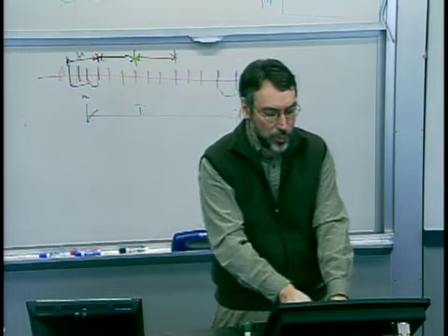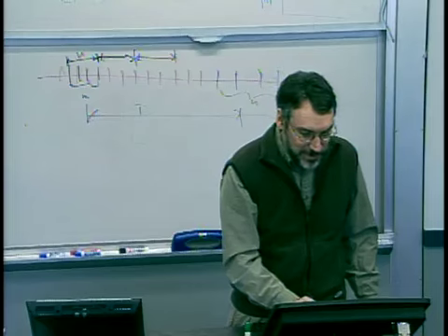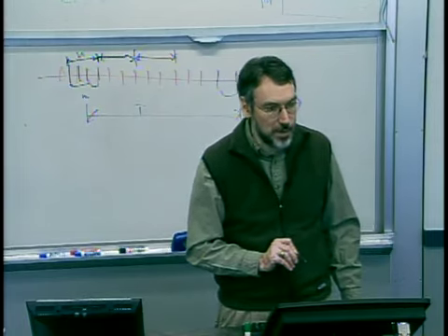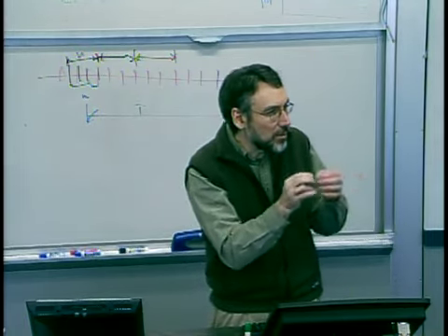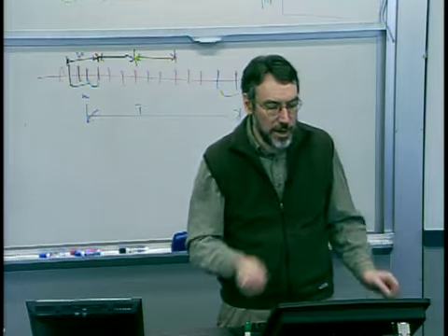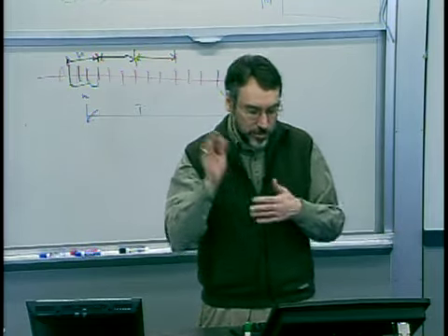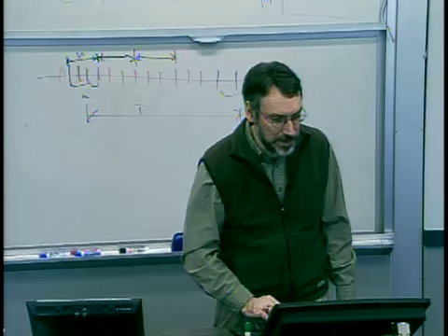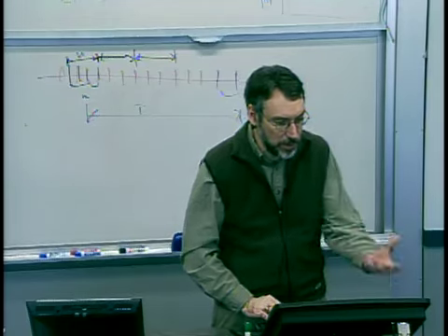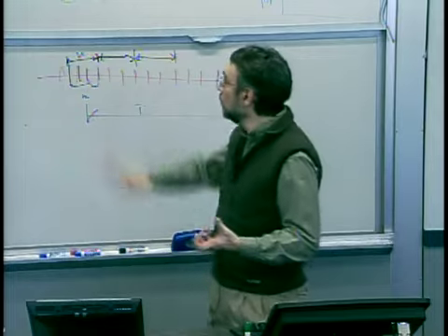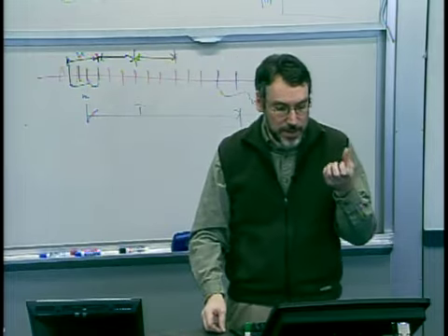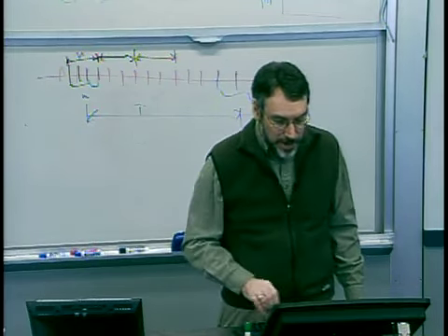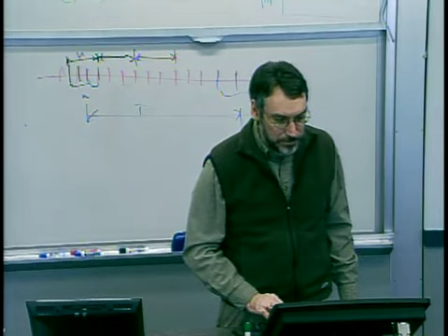And all this is saying is you want to pick your sample time ultimately such that if I pick this sample here and then at my sample time some point later, this underlying sort of short-term correlation is not what I'm detecting. I'm detecting again a big mean shift. So we've been talking about this. Again, what you're looking for here is maybe pulling your small sample out, using in fact some of the correlation there to be able to say what the best estimate of the mean is right at that point in time, and then have uncorrelated samples around that.